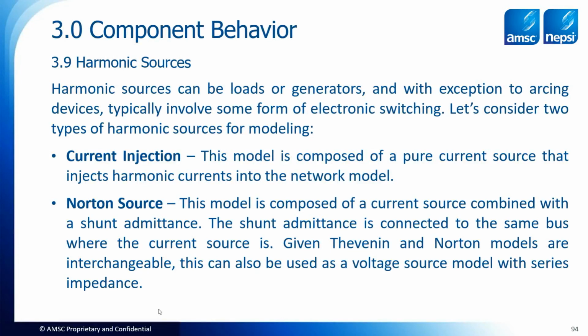rather than just lookup tables inside a power system analysis tool where you put in the length and the type of conductor, 500 kcmil, and then it comes up with R and X for you. Maybe you've got some real detailed data from the manufacturers on the exact amount of ohmage per 1,000 foot. And you put all this in, you build it absolutely perfect. If your sources of your injections are wrong, it's wrong.